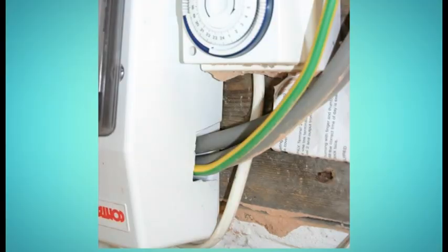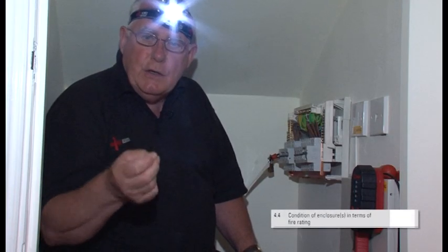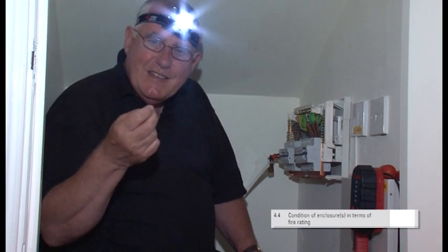A common example of where it wouldn't be okay is, for instance, where a knockout's been removed to allow cable entry. Unfortunately, if this meant that a live part could be touched, it would have to be classified as a code C1 on the report. Our next item is the condition of consumer unit enclosure in terms of fire rating. Now, this isn't a problem